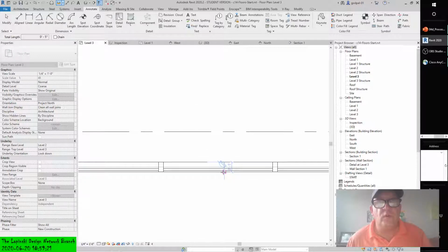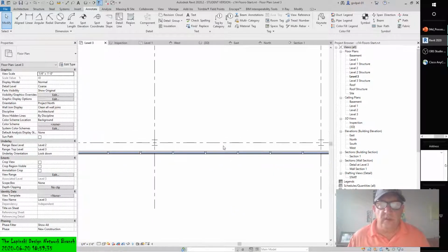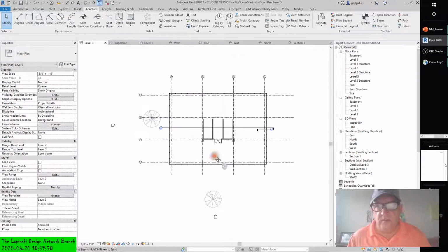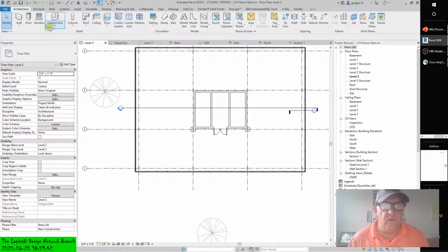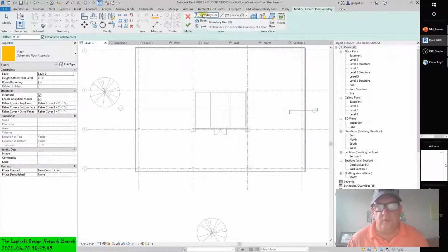So we place this floor. You'll see in elevation just how the floor is going to align with the mullions and give us maybe just a 1/2 inch difference between the two. And it's a lot easier to show you than it is to lead you along. So let's just remember that. Let's go back to the Architectural tab and invoke Floor Structural through the Build panel. In the options bar, or in the contextual toolbar, first make sure Boundary Line and Pick Walls is selected and offset at 3 inches.